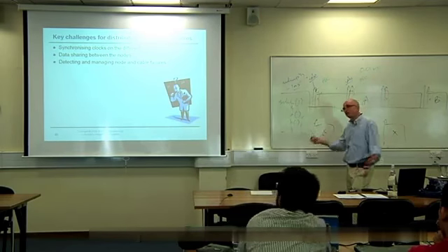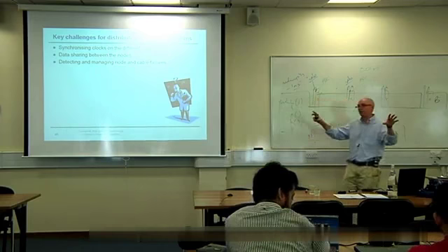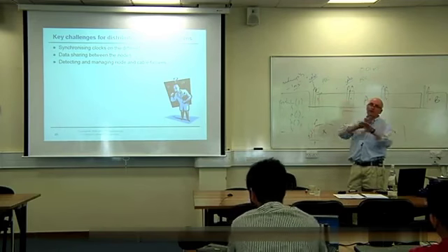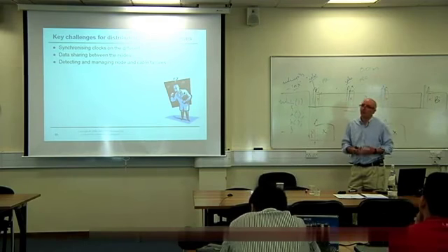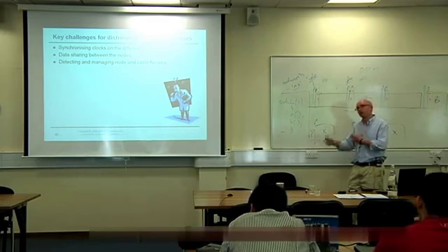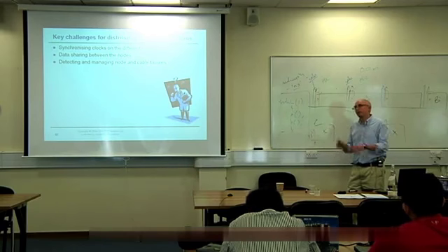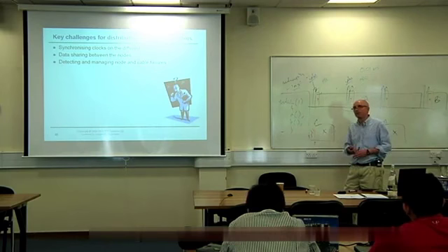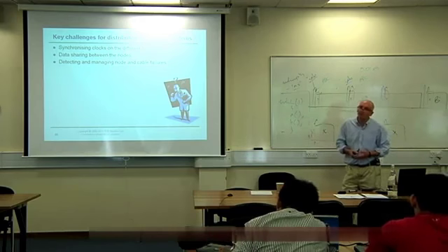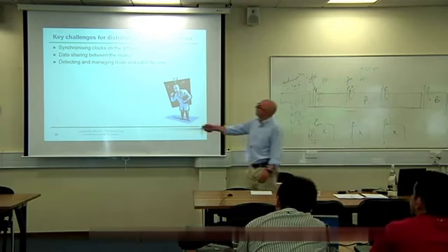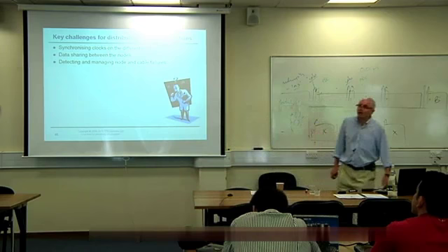Sometimes what people do is put a couple of nodes together. They put CAN connections. We'll talk about what CAN does, but it's essentially a serial communication protocol if you've not met it. And they just send messages between the nodes. When the messages arrive at a particular node, they generate an interrupt. And that's a common behavior. And we say, okay, have you thought about the timings at which you're transmitting the messages? No, it doesn't matter. We just let the messages fly around the bus. We make sure the bus is not overloaded, and we deal with the messages when they arrive. It's very difficult then. You've got a whole bundle of events happening at random times coming through that system, and it's difficult to predict what's happening. We need ways of synchronizing the clocks, sharing the data, and detecting and managing errors in this system.